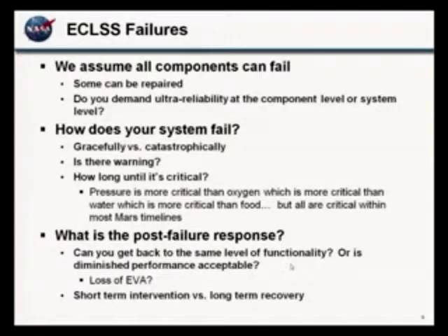So do we on space station. They're both electrolysis. Everybody has tanks of oxygen. That's dissimilar redundancy. And then you have your oxygen candles, which are not going to require power, not really even require control. When you turn them on and start that reaction, oxygen is coming out. So if your sensors are down and your valves are all stuck, you're still going to get oxygen out of that candle.